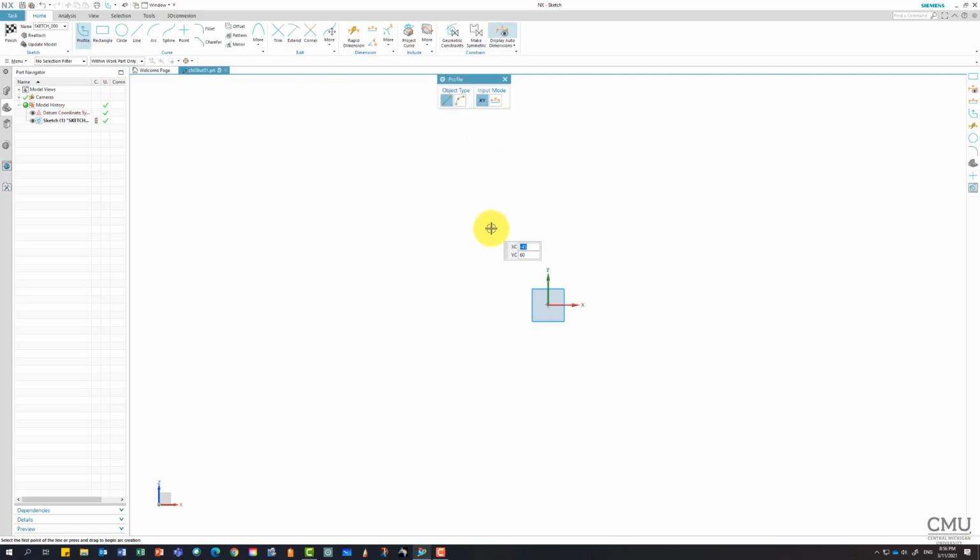I'm going to use the left lower corner as the sketch origin, and I'm going to use a profile. Unlike in chapter 2, from now on I want to use the mouse instead of the keyboard typing method, but be aware that you should try to get the approximate size as much as possible. Don't make it too small, don't make it too big. Just focus on a close enough size with the mouse point, because everything has to be by mouse click. It will likely produce lots of auto dimensions. Many dimensions are not going to be confirmed. That's why later we are going to add more geometrical constraints.